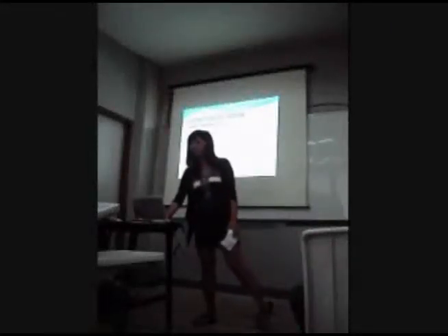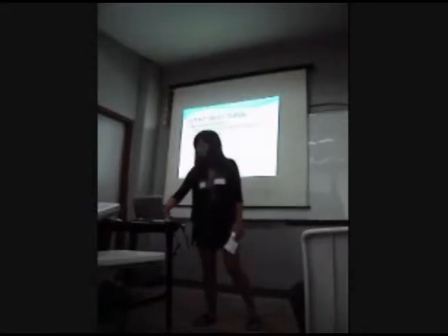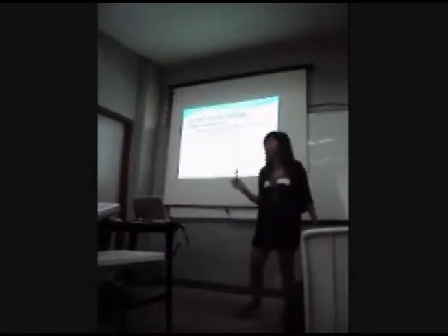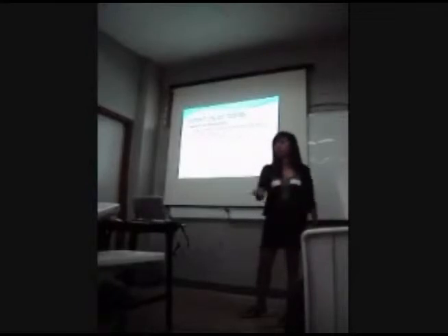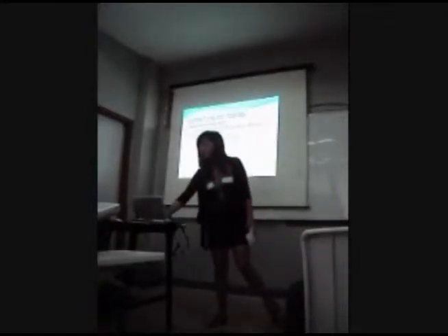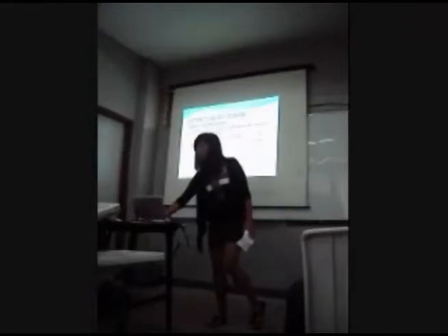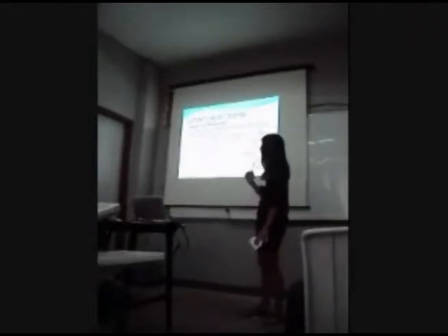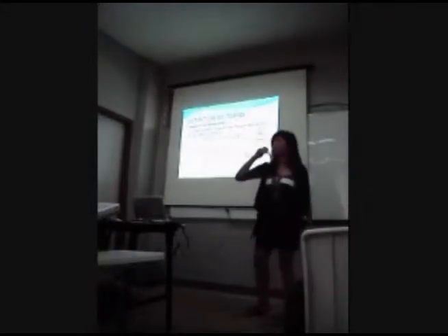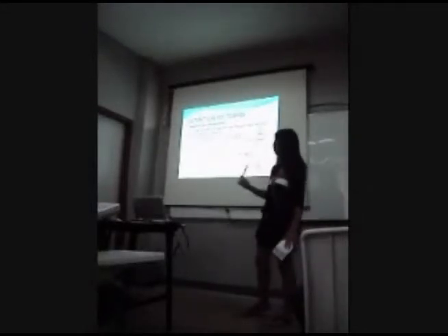So, definition of terms. Some of these terms will be used throughout our report. The liquid to gas ratio, or the quantity of liquid fed to the absorber divided by the outlet gas flow rate. So liquid in over gas out.